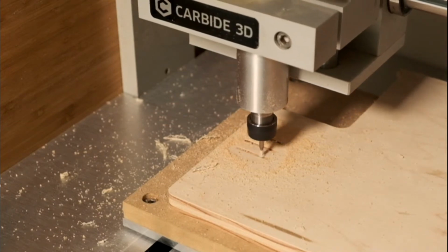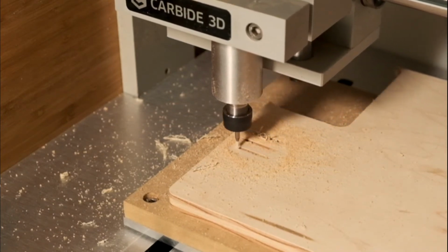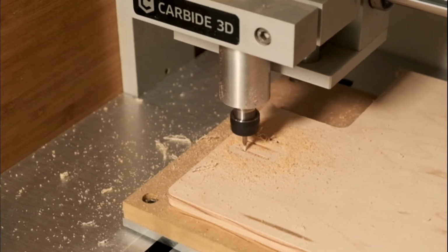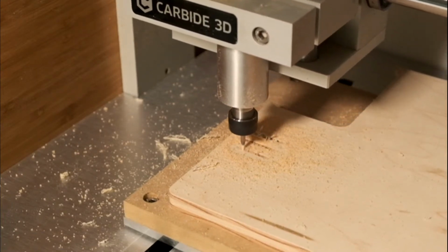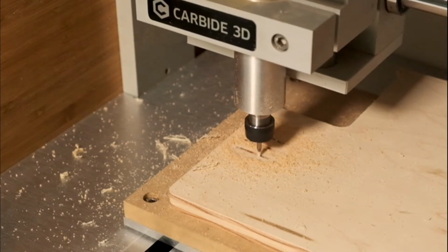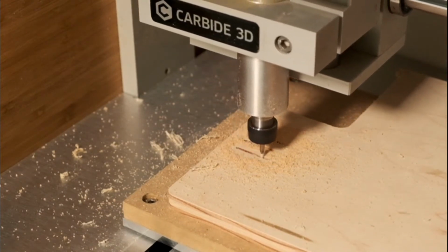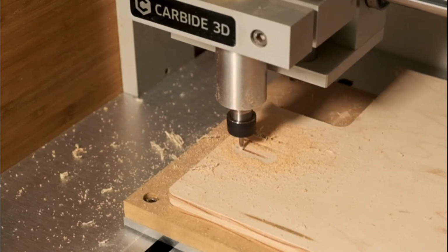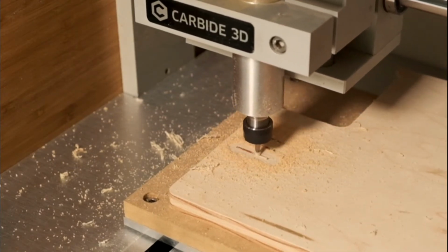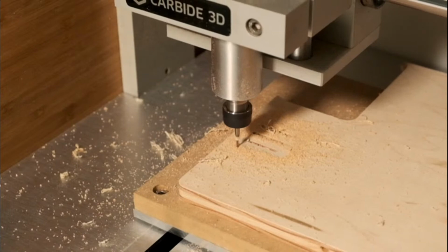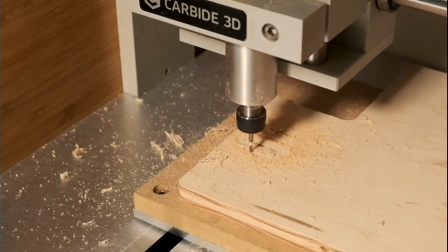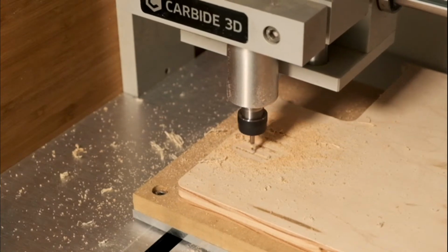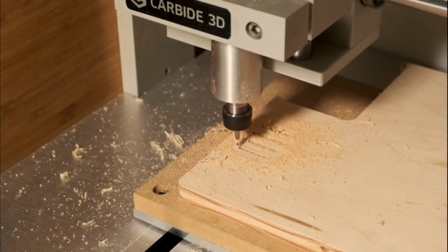Quick intermission. I'm just going to jump in here and bump up the feed rate by probably 40%, just because it sounds like it's going pretty well, so that should help it complete faster. The decision to increase your feed rate is totally subjective, but if it sounds like your CNC is not having any issues whatsoever, feel free to just crank it up. The worst you're going to do is break an end mill, but in a really light plywood like this, you can push it pretty hard.